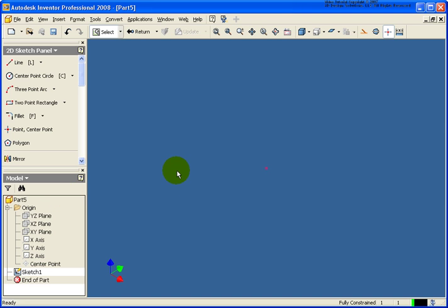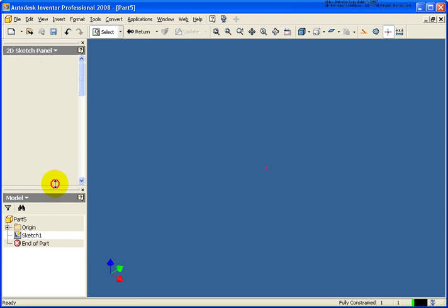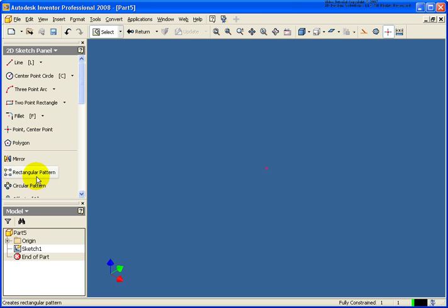The last thing that I wanted to point out here, I'm going to minimize the origin folder. When I'm in Sketch 1, you'll notice that everything else is grayed out above it and below it. But I also have my sketch tools. They are all available. So for example, I'm just going to place in a quick rectangle here. You'll notice that I'm drawing it in an isometric view. And of course we can go back and use our Look At tool that we learned about in a previous lesson. If I just select Sketch 1 in the browser, I can look at that from that parallel plane, if you will.